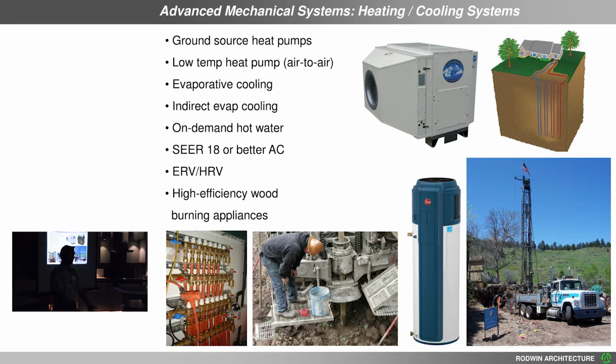An ERV, or an HRV, energy recovery ventilator or heat recovery ventilator, this is something that is new and really important and special. Remember we talked about holistic design again. If you seal up a house really tightly to make it super energy efficient, and you've got products that have some toxic off-gassing, because every house has some, whether it's the paint, the carpet, the cabinets, the flooring, the plastic around the light fixtures, there's always a little bit, even in a good green home.